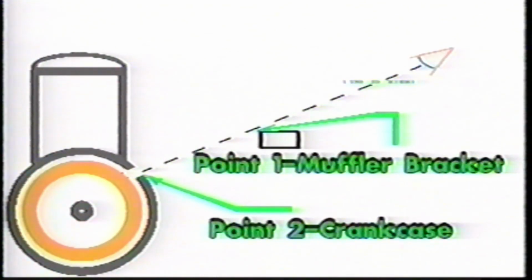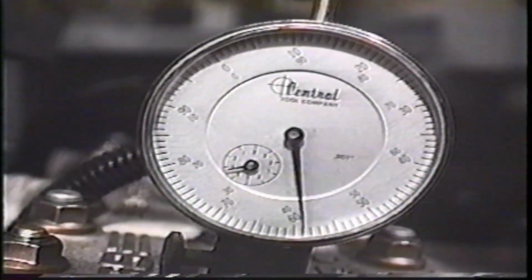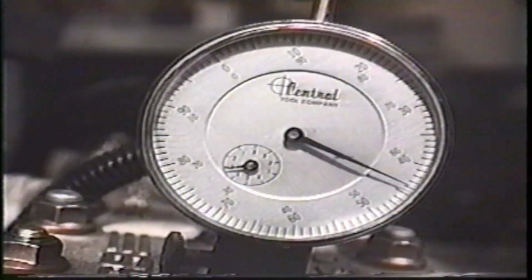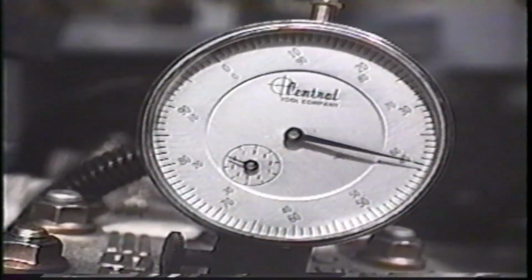Use the gun sight method to line up 2 points for best accuracy. Observe where the black circle is in relation to the hole opening. If your mark does not line up, stop the engine and reinstall the dial indicator in the mag cylinder. Find top dead center and rotate the crank, counting the distance the dial moves until the mark is in the exact position you observed with the strobe light. Compare this number to the chart in the Master Repair Manual.